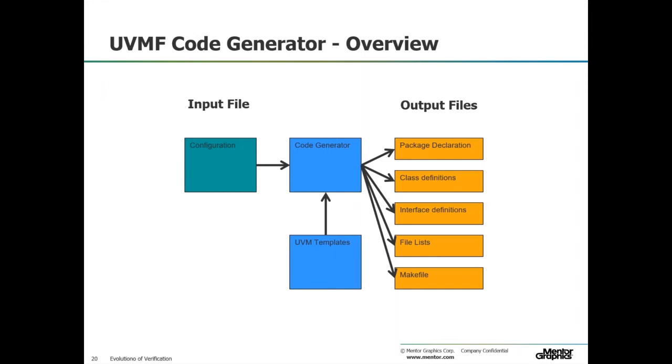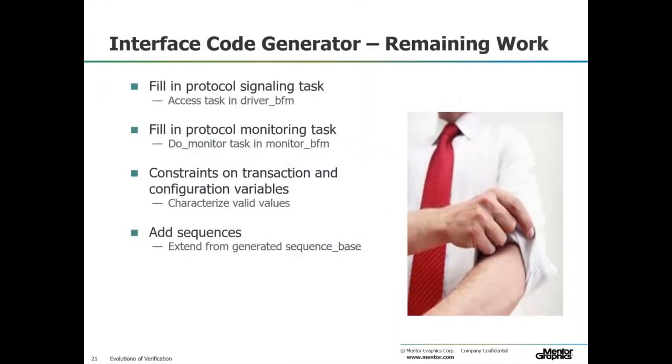So I go back and I create one of those templates for each agent. I create one of those relatively simple templates for my environment and for my test. And then what comes out the other end is a make file that I can just say make, and that will compile and actually launch that test bench so that you've done as little as possible and had to create as little code as possible. And then you just have a few tasks that you have to do. And they're tasks that a Verilog coder or VHDL coder will be more familiar with.